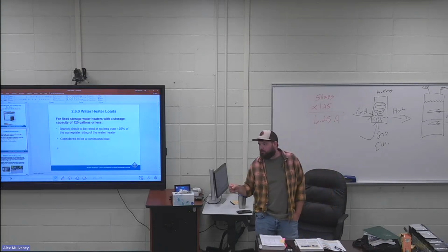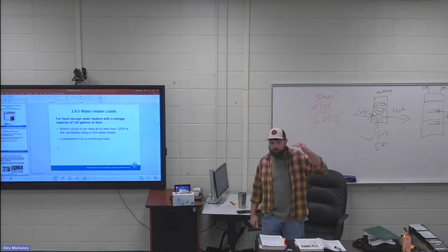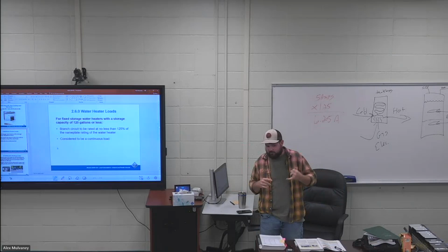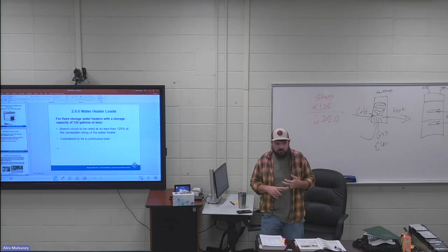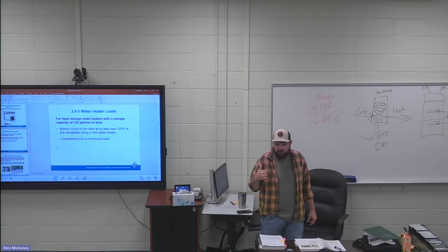What I would highly recommend when you guys are going through this, write on a piece of paper, continuous duty, non-continuous duty. What are some continuous duty loads? Heaters for your house, baseboard heat, water heater, storage type water heaters. Those are always going to be continuous duty loads. All right.